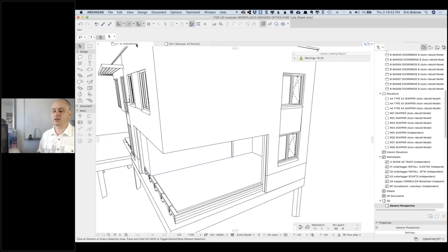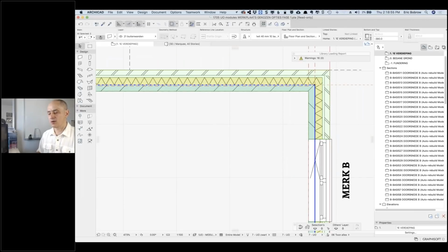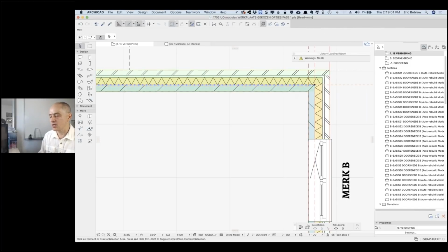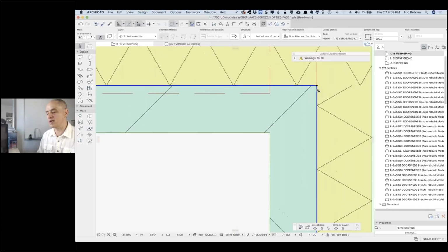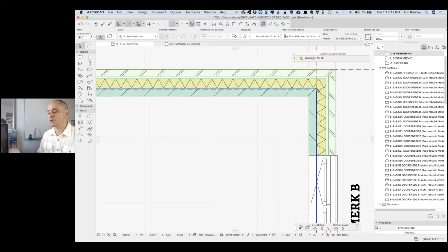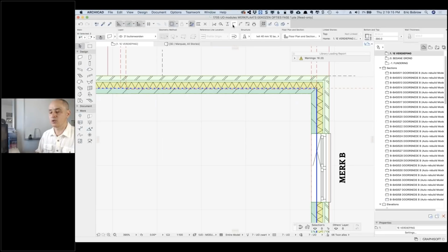The things that I look at are, if things aren't cleaning up, I'm going to select the walls like this and look to see that the reference lines are actually meeting at a point. And if necessary, I'll zoom way tight in. Of course, if they're off, you can manually adjust it, or you can use this intersect command. Now, if the walls are made of different types of composites or different components, then that can cause some complications. But it looks like these walls are very similar to each other, and so meeting at a corner should be very natural, right?